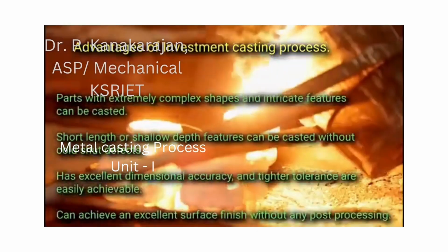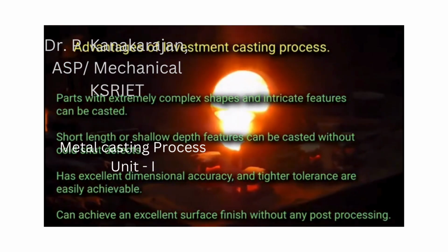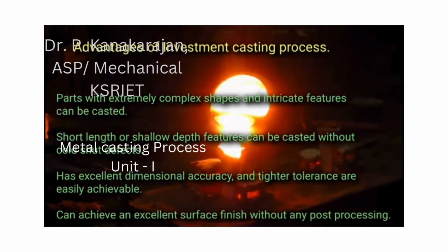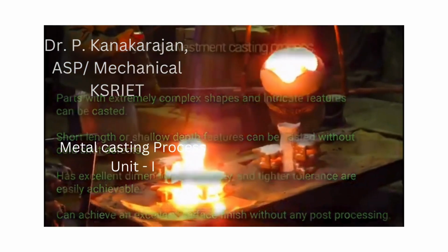Short length or shallow depth features can be cast without cold shut defects. It has excellent dimensional accuracy, and tighter tolerances are easily achievable. It can achieve an excellent surface finish without any post-processing.